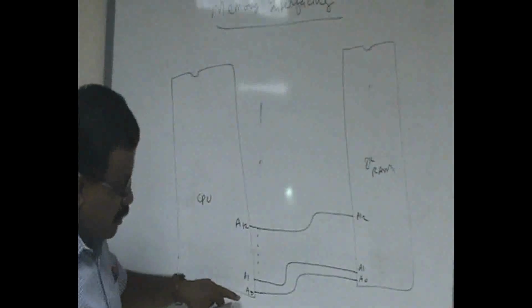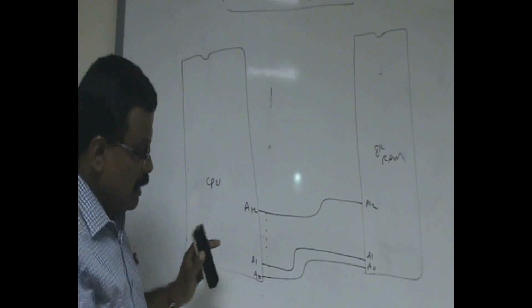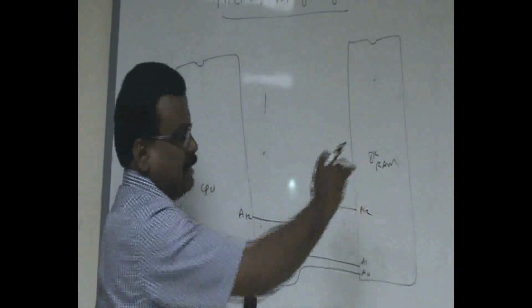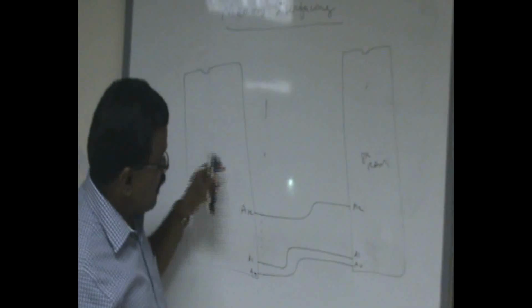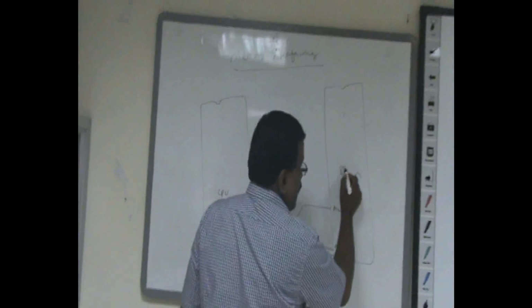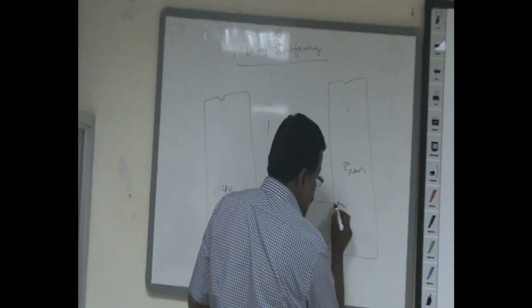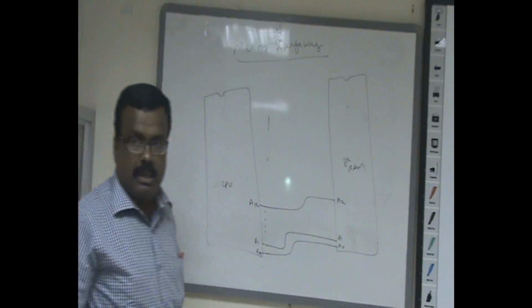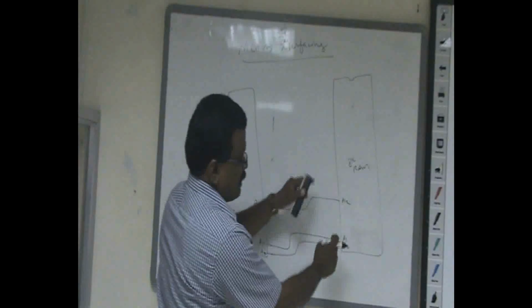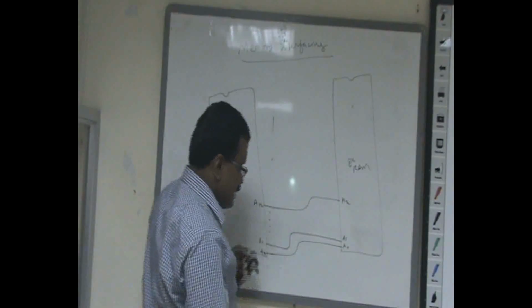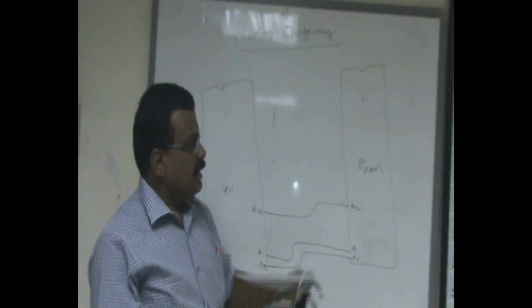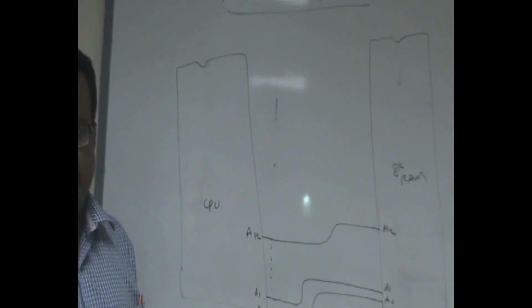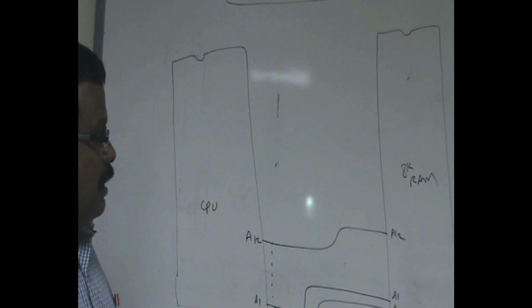Actually, in 8085 you will have only AD0 to AD7. That should be latched. After the latch you will get A0 to A7. Then A8 to A12 can be directly taken from the CPU. If you look into the pin diagram of 8K RAM, there is a provision to connect 13 address lines, so you can directly connect these address lines from A0 to A12. The idea is, by varying between 13 zeros and 13 ones, you will get the 8K different locations.